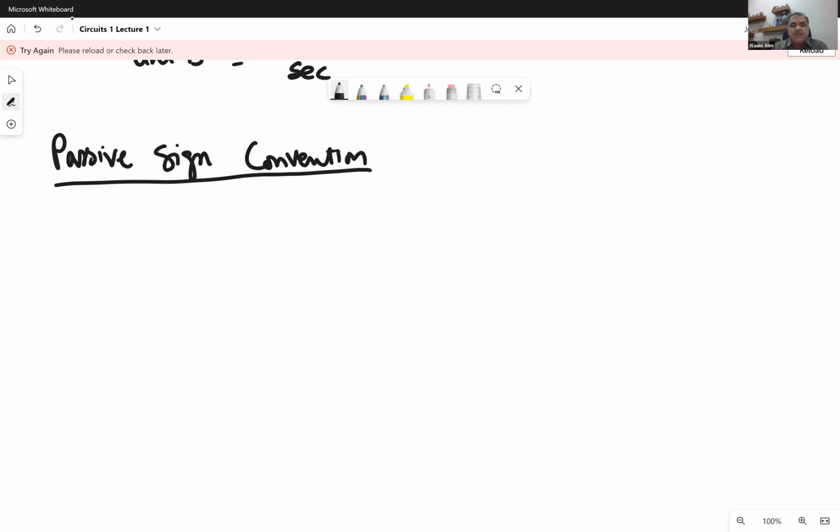A typical example of a load is going to be a resistor. So whenever we use resistors in our circuit, they absorb energy, and you could see it in terms of heat. Whenever you have a circuit running for a while, if you touch a resistor, it typically would be a little bit warmer, and that is just a sign that it is absorbing energy. Okay, so the passive elements are loads in our circuits, and what they do is they absorb energy.